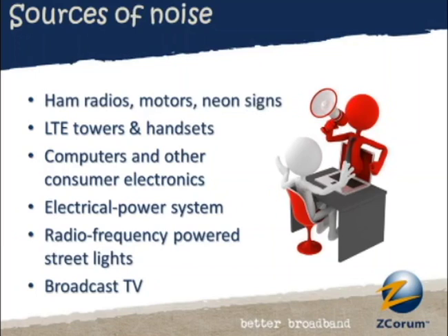And do these devices or these interference sources, let's say they're not on this list, but if they're not at the same frequency, does that matter or not? Well, it needs to be the same frequency once it's on the cable plant, one of the bands that we use either in the upstream or the downstream. But it doesn't necessarily have to be the same frequency as it's emitted.